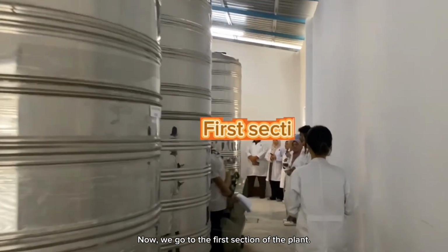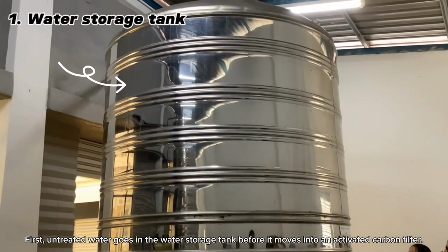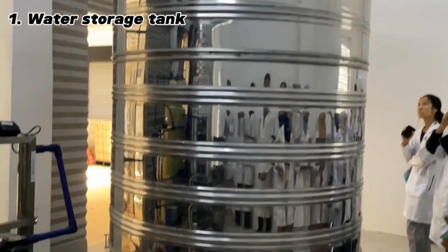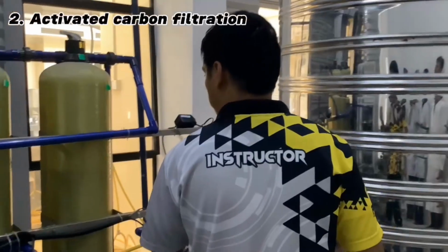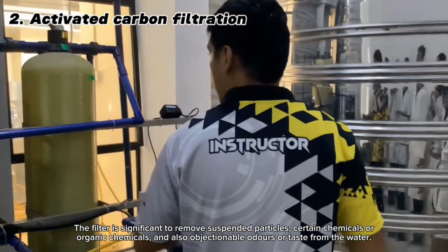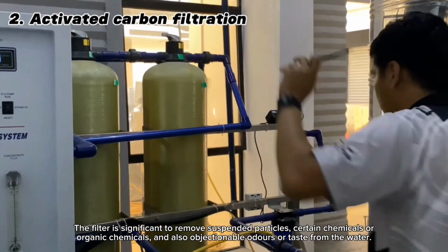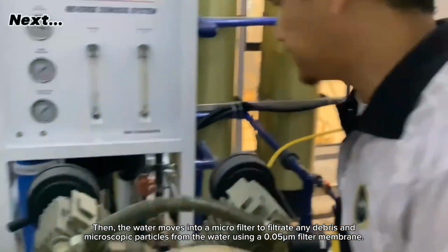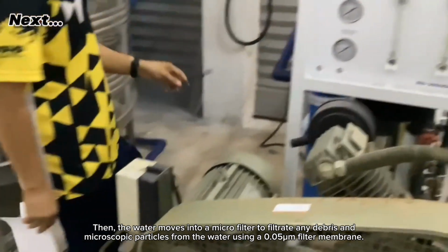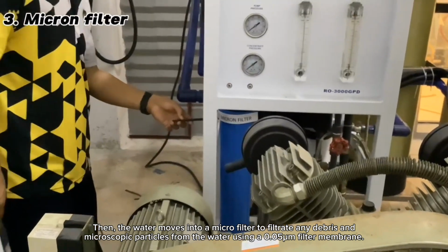Now, we go to the first section of the plant. First, untreated water goes in the water storage tank before it moves into an activated carbon filter. The filter is significant to remove suspended particles, certain chemicals or organic chemicals, and also objectionable odors or taste from the water. Then, the water moves into a microfilter to filtrate any debris and microscopic particles from the water using a 0.05 micrometer filter membrane.